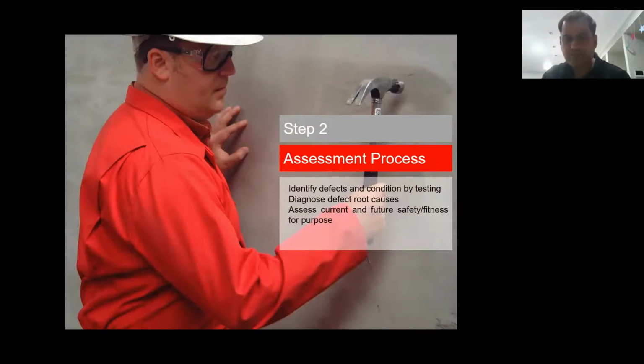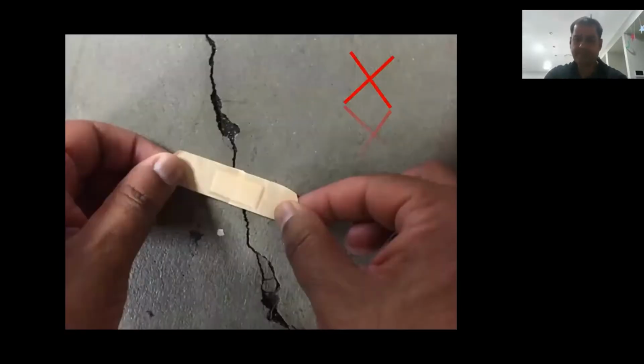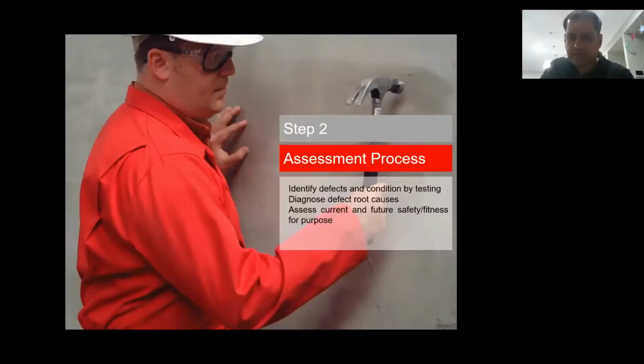So what I'm trying to say is, in concrete repairs, there is no room for cosmetic repair. There is no room for a masala mortar. There is no permission to be superficial and just do a cosmetic touch-up repair. It has to be addressed as per the root cause, and you need to understand what the root cause of the problem is. This is more applicable for old and existing structures. For new structures, we know that it's new: honeycombing is a defect, workmanship, shrinkage cracks or drying shrinkage, and these types of problems.